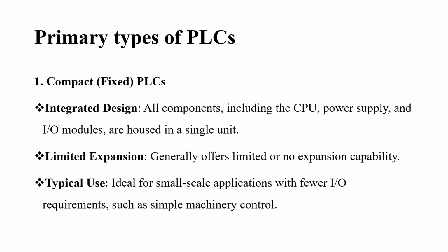Now, one of them is the fixed type of PLC, and that is the compact type. This compact type has an integrated design in a way that all components, including the CPU, the power supply, and the input-output modules, are housed in one single unit.